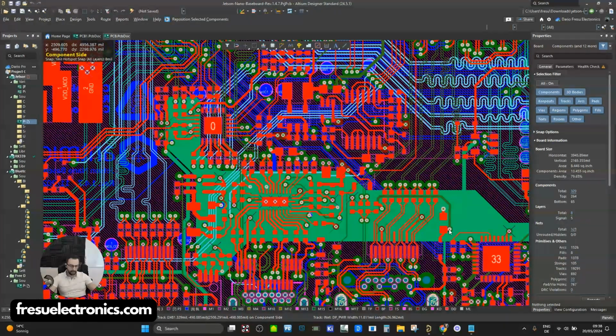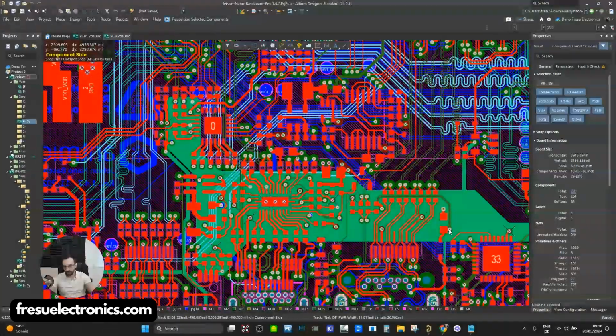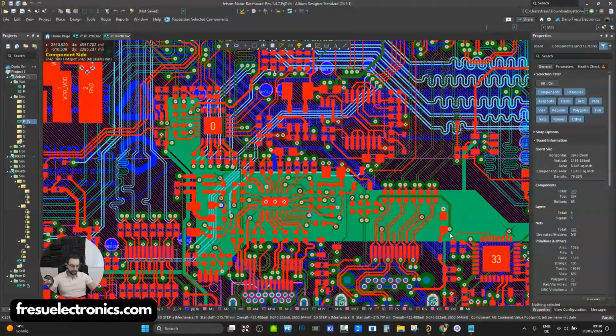So then the second requirement is to avoid any AC noise within the power delivery network. This is important because otherwise this noise can spread throughout the whole PDN, and then it will reach the ICs, so we will have some signal integrity issues, or it can also spread around and cause some EMI issues by coupling through the cable or radiating. So then the next requirement that we have is a 0 ohm AC impedance between the power source and the return reference plane.